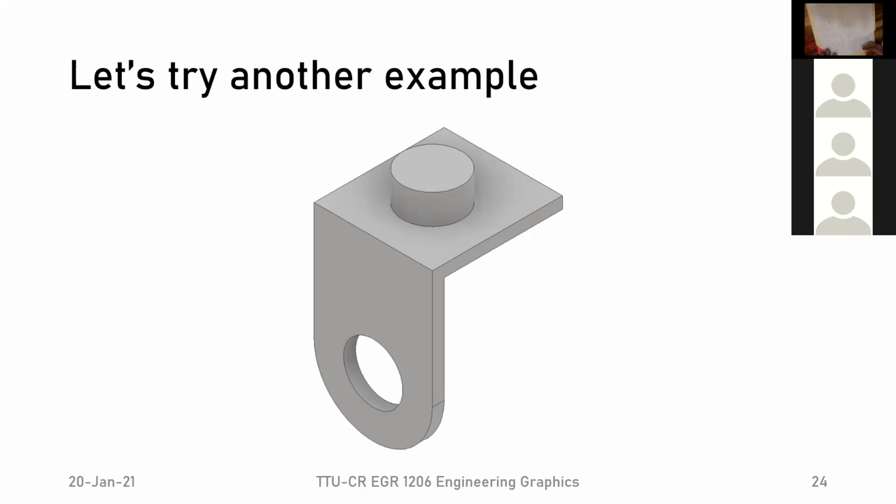Now, one thing that's very important to remember: if I'm looking from the side view, in this direction onto my piece, then I don't see that this is curved. There's nothing there that tells me that it's curved. The same way that when we looked at our other object here, we can't really see, if we're just looking straight, whether this part goes straight up, is angled in, or gets angled out. It doesn't matter. All we can see is that it starts here and it ends there. So that's why we do a straight line all the way down.